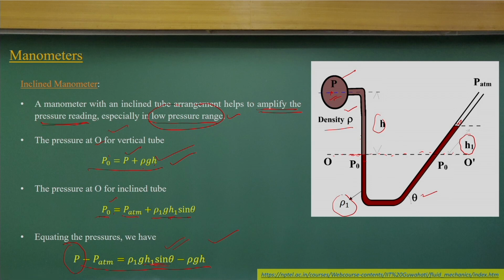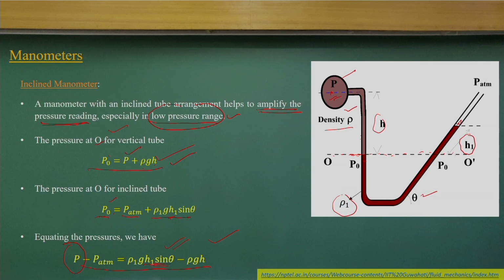As you remember, the wind tunnel I showed you in the third class uses inclined manometers to measure the pressures. So, this is the same concept of inclined manometers, used to measure low pressures, and which is very easy.